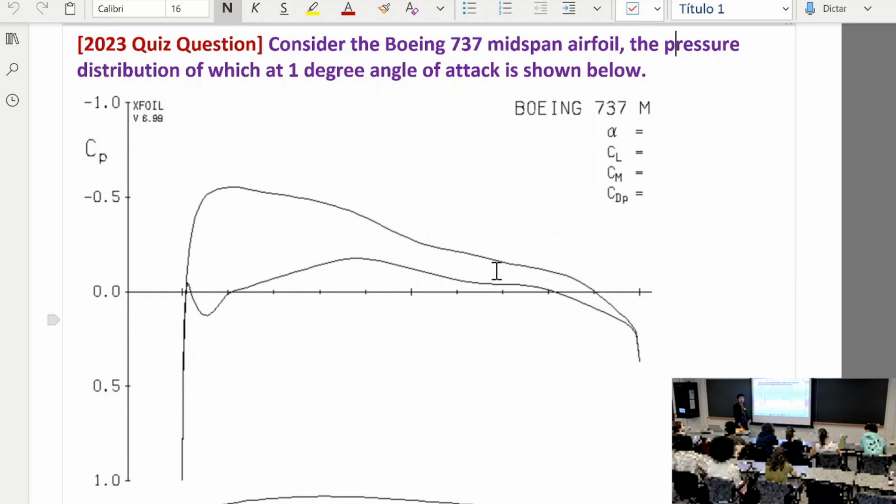That's how I remember it, and I think it's the easiest way to remember how the pressure coefficient is non-dimensionalized: relate this to velocity using Bernoulli's. So lowest velocity, 0, CP equal to 1. And the free stream is going to be 0. Anything above is higher velocity than free stream.